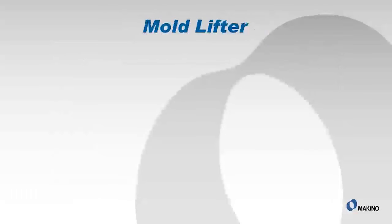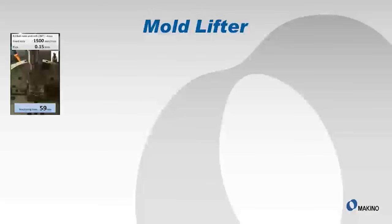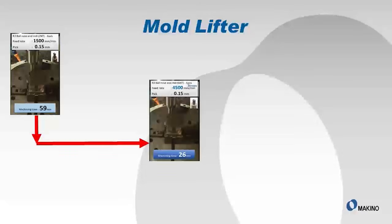What I've done is taken the mold lifter statistics from the videos and put them together in a little chart here. You'll see the first one where we ran it with a 2-flute at 1,500 millimeters a minute. Cycle time was 59 minutes. Then there was a second where we ran it with a 6-flute, 3 times the feed rate, 4,500 millimeters a minute, and it was 26 minutes. So you can see there we've reduced the cycle time by 33 minutes, which is almost a 55.93, 56% reduction in cycle time.